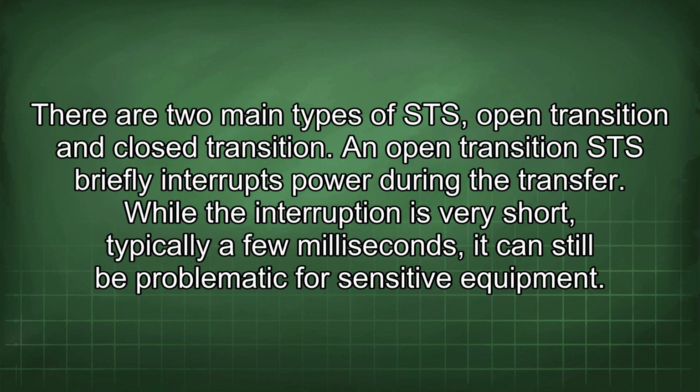There are two main types of STS: open transition and closed transition. An open transition STS briefly interrupts power during the transfer. While the interruption is very short, typically a few milliseconds, it can still be problematic for sensitive equipment.